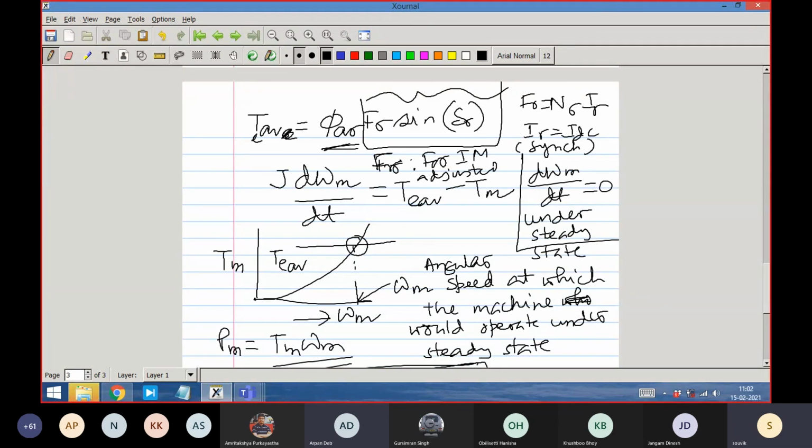I will show you. You are just taking a 90 degree shift, and eventually the angle between them becomes the same. That I can show you later. They become the same because flux to voltage is a 90 degree shift, and MMF to current is a 90 degree shift, and then they become equal. Is that okay? Yes, sir. So ultimately the power is VI cos phi, and here the angle is 90 degrees minus phi. So therefore it is sine of delta.